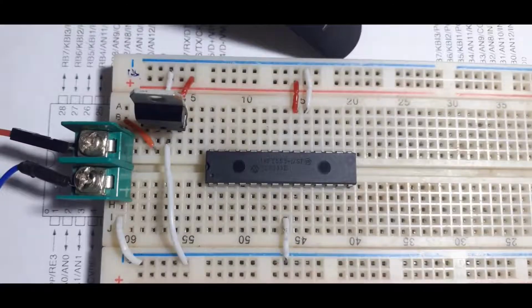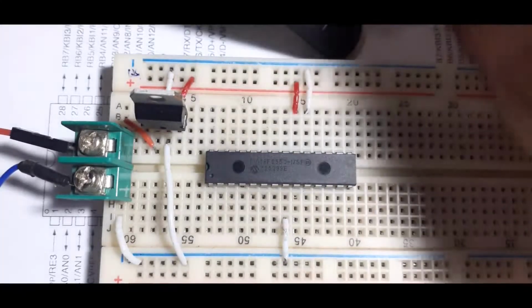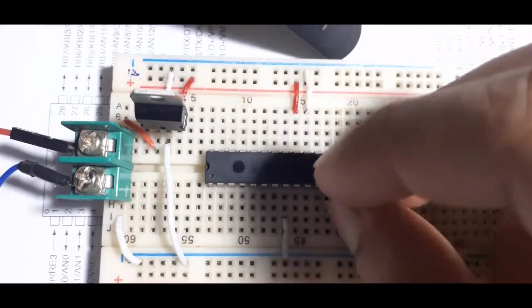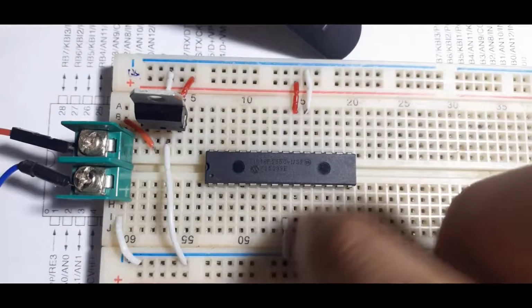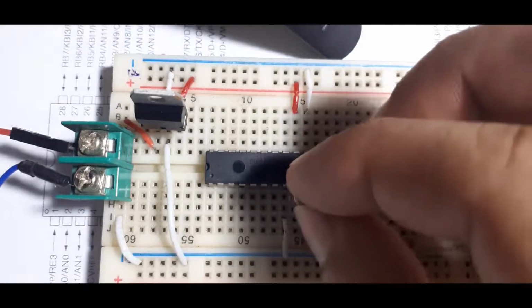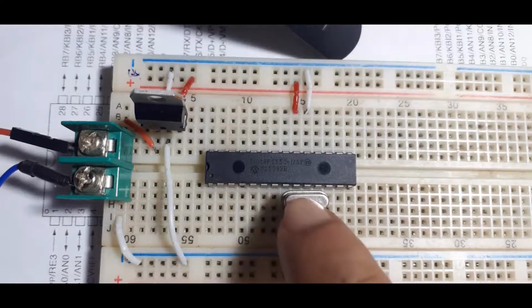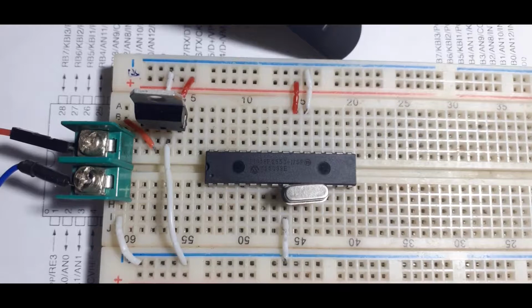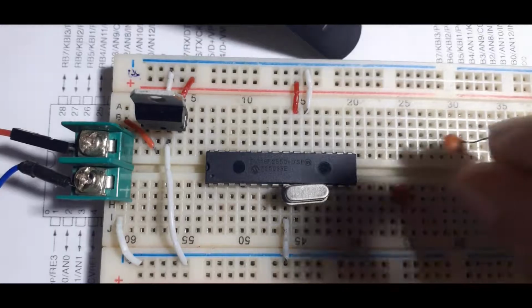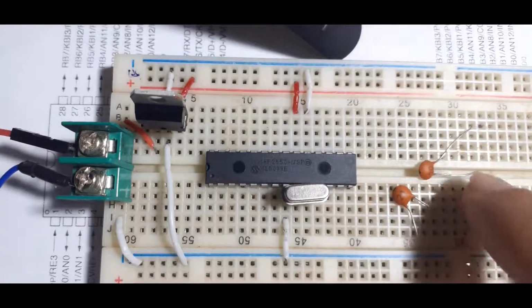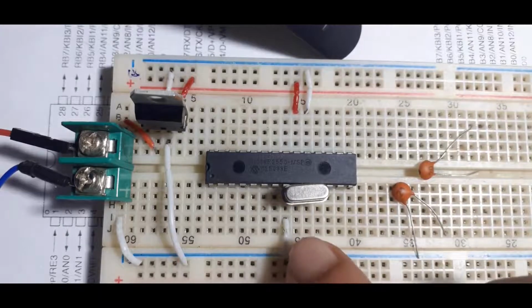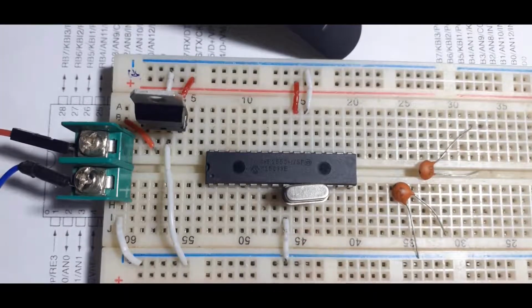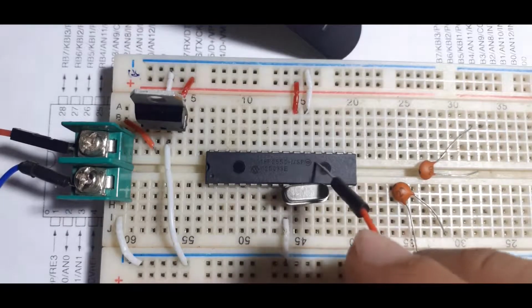The next thing we're going to do is connect the oscillator. Here is the oscillator, and it's connected to the pin directly after the ground. So here we go. Just make sure that you connect the oscillator as close as possible to the microcontroller pins. But there is one little thing I haven't mentioned, and it's that we need 2 capacitors here, about 20 or 22 picofarad capacitors, to connect between the oscillator and the ground pin. And why do we need them? Just to have a stable clock source entering the microcontroller pin.